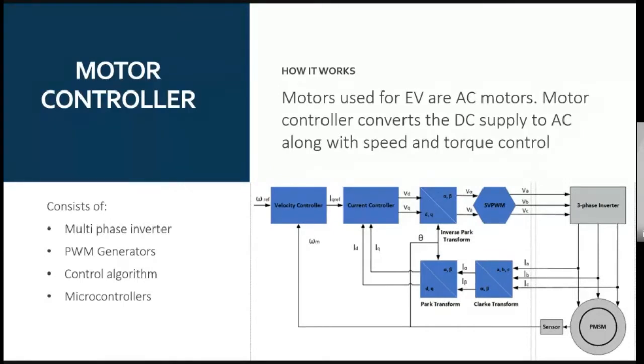There were some mistakes when selecting controllers. Some select Arduino or other controllers for applications that are not suited for motor drives. That means there is no motor control PWM inside Arduino. But we can see that some people are working on Arduino for motor control applications. That means there will be less performance in that motor drive.